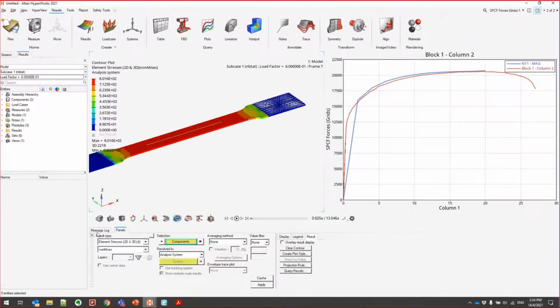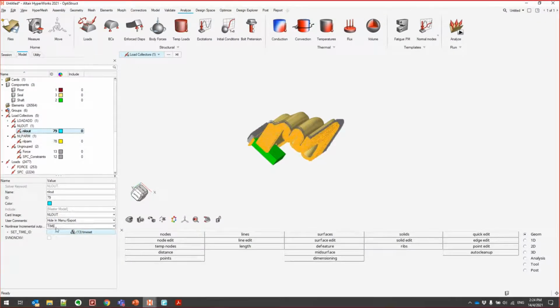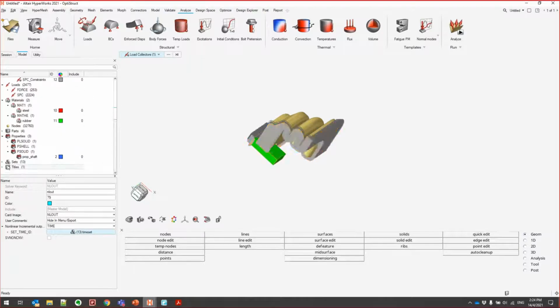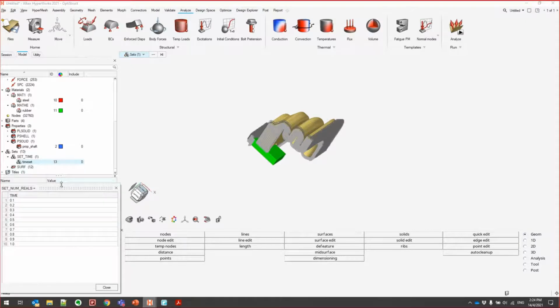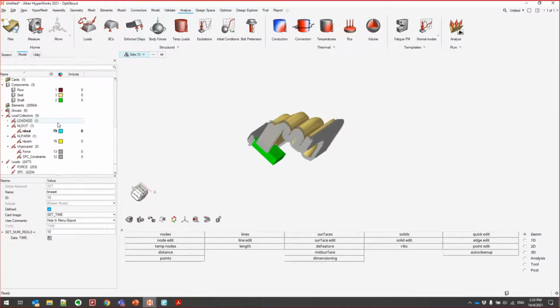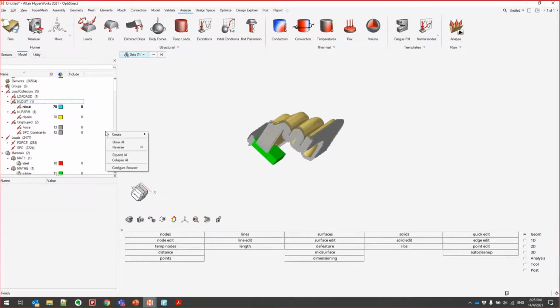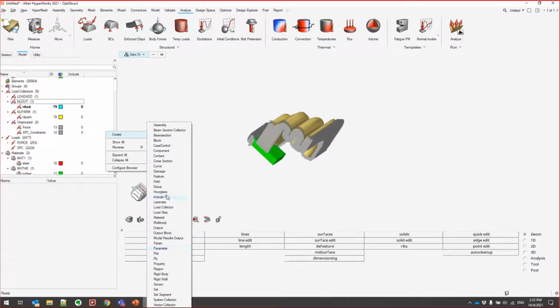Now we are going to output. Let's go back to here. Our NLOUT is going to output at what time, based on this set time here. So the set time is created under the sets. Yeah, this time set here, which we have created earlier. So it's going to output exactly at these times here. Okay. So now NLOUT is done. Now I can create the rest, NLADAPT. Okay. And then if you want, otherwise I'll just go straight to creating that load step.